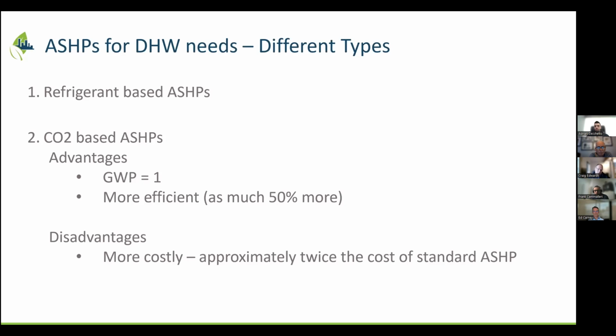And then in larger buildings with a larger domestic hot water load, we've been designing them with larger heat pump systems, 410A and 134A systems we've used on a few projects, and then also CO2. We'll talk about the CO2 example at an outdoor pool, but we've got a couple of other projects under design right now, a new community center where we're putting in a CO2 based heat pump, and we're retrofitting a large housing project with a CO2 based heat pump. So we've got experience with all of them.